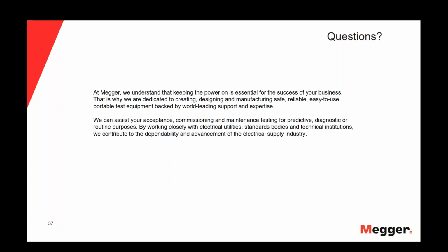It could be chemical aging. Whatever breaks up the molecular structure of the XLPE insulation and affects it will be measured by measuring the dielectric losses in the insulation.